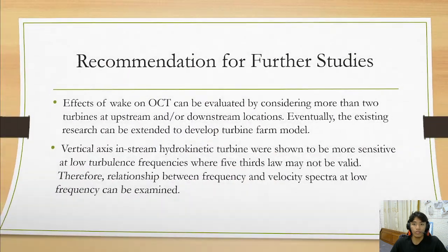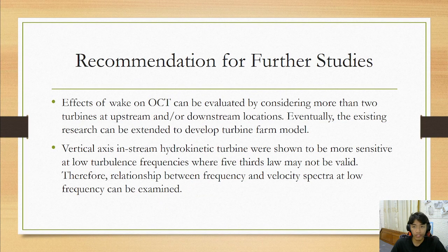Okay, so there are also some recommendations for further studies. The first one is that effects of wake on OCT can be evaluated by considering more than two turbines at upstream and/or downstream locations. The next one is that vertical axis in-stream hydrokinetic turbines were shown to be more sensitive at low turbulence frequency, where the 5/3 law may not be valid. Therefore, the relationship between frequency and velocity spectra at low frequency can be examined.